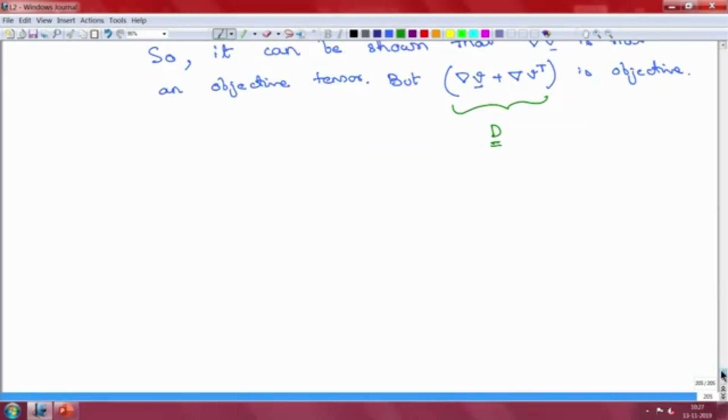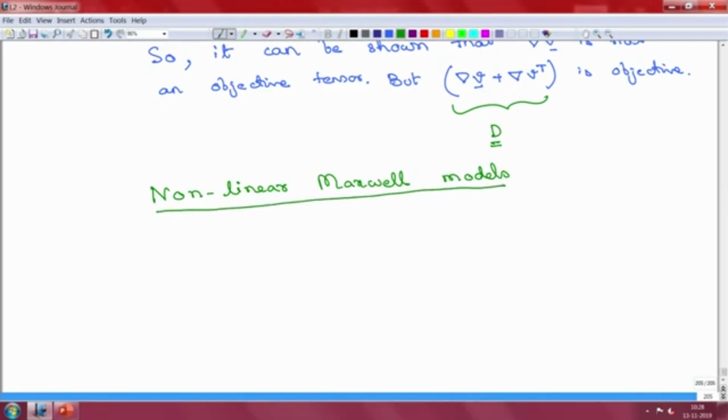So, what happens is that the Maxwell model can be generalized to other forms, to what are called nonlinear Maxwell models, and you can generalize them just by using the expression that we had used before. Okay. So, we had some lambda, which is a relaxation time scale or a characteristic time associated with this, and then we had a derivative. Okay. So, some d dt here. So, I am just going to write d dt right now of the stress tensor. So, now we are generalizing it. So, it is no longer one dimensional. So, that is why we have to use the tensorial form plus